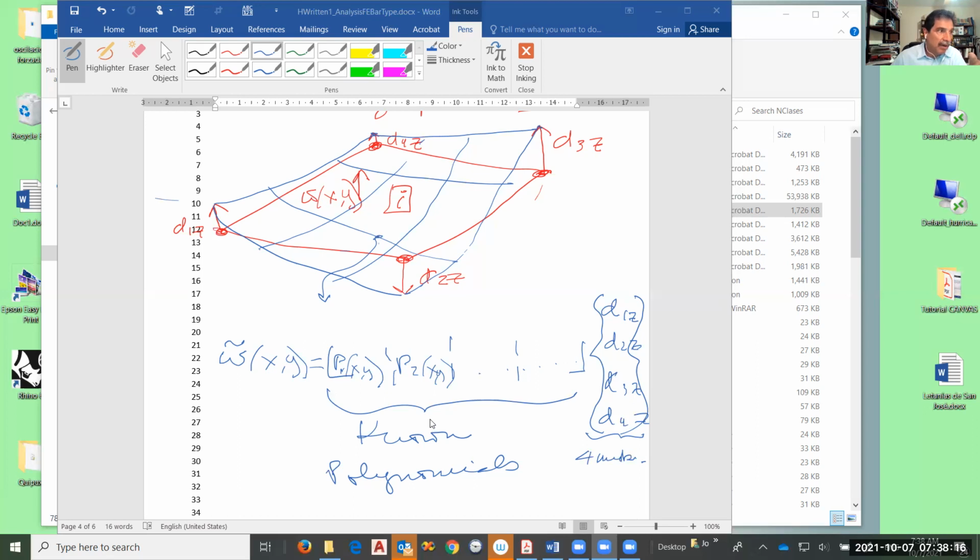When you use a program, you cannot change this. What you can change is the number of joints, but these polynomials you cannot change. So you have to have that in your mind. If you expect a function which varies a lot in a certain area, that means that if you try to get close to that curve, you have to use small elements. Okay?